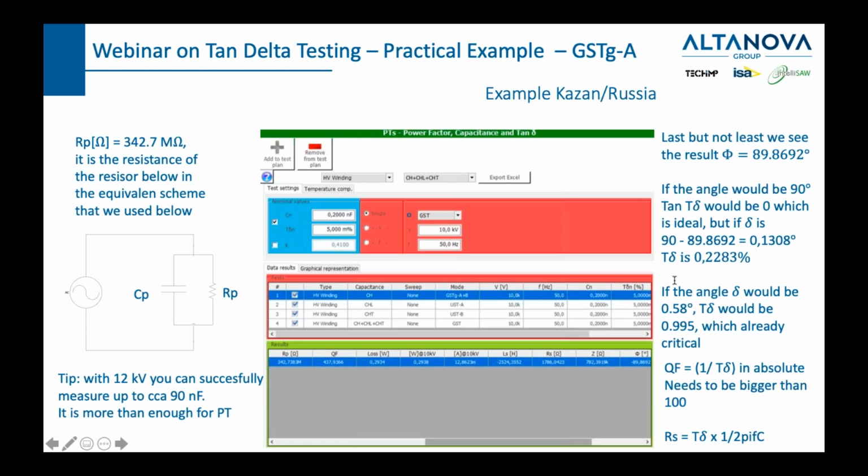You see, if you want to do a tan delta test, you need to generate voltage and you need to measure the current. So you need to disconnect. But in the case you are describing, I propose continuous monitoring of tan delta. That is something we also provide. You put sensors in the tap adapters, or you can even put in the monitoring of partial discharge at the same time. And then you have a trend of tan delta and partial discharge, which will tell you exactly what stage your insulation is in. So for this case, I propose installing the monitoring solution.